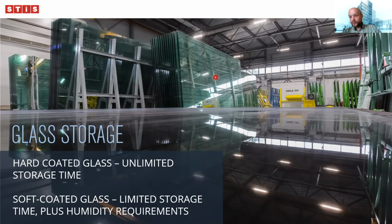Soft-coated glass has limited shelf time: half a year, 1 year, depending on the coating type and depending on the conditions in the warehouse, mostly humidity and temperature. Also, in terms of glass cutting, hard coatings don't require edge deletion. Soft coatings, most of them do.